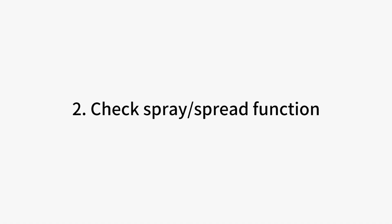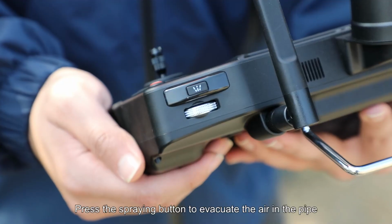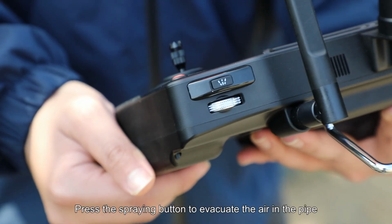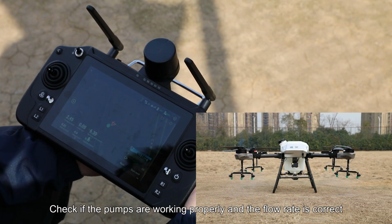2. Check spray or spread function. Check sprayer with pressure nozzles. Press the spraying button to evacuate the air in the pipe. Check if the pumps are working properly and the flow rate is correct.